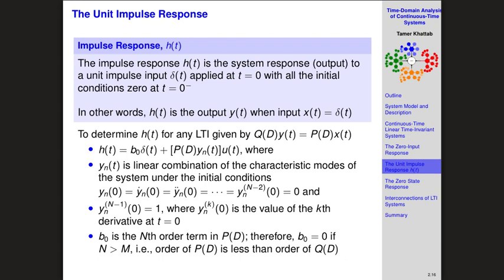So what's the other option? If I know the differential equation that represents the input-output relation of the system, I can actually calculate the impulse response of that system. So for a linear time invariant system, if I know the input-output relation, back to this equation, using the generalized differential equation representation, okay?